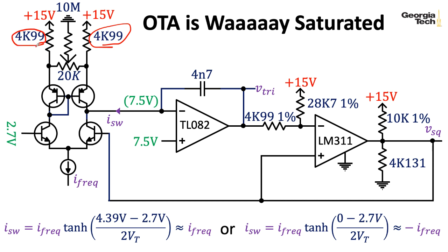Oh, something that I should mention, I'm using this convention of using the unit, like K, to replace the decimal point. So that keeps the notation compact. And also means that if somebody is somehow, for some reason, reading a photocopy of these slides, if a decimal point gets lost in that copying process, somebody doesn't suddenly think it's a 499 ohm or 499K resistor.